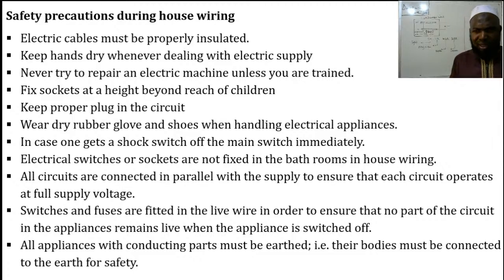And lastly, all appliances with conducting parts must be earthed. Flat irons must be earthed. Kettles must be what? Must be earthed. All those ones with touchable appliances must be what? Must be earthed. In order to ensure that we don't cause electric shock.